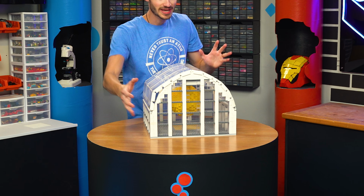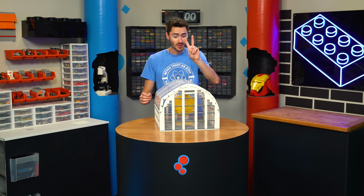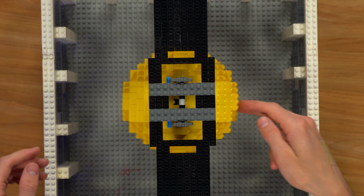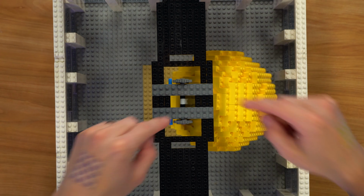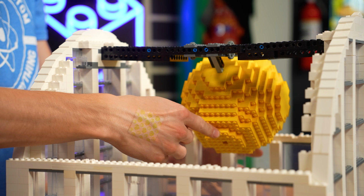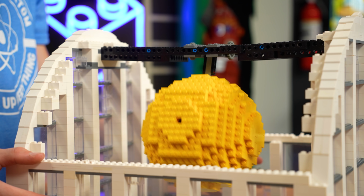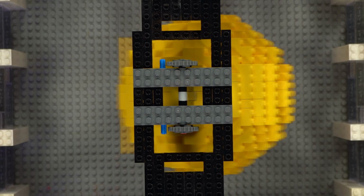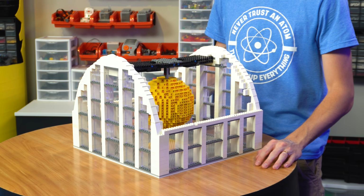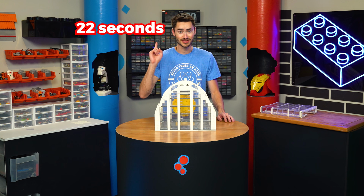So here inside this, we have our tuned mass dampener. And there's actually two ways we can tune this to make it match the fundamental period of the building. As you can see, it's just a big 4-pound ball that swings back and forth, but I've connected it to these gears up here. And right now, the gears aren't attached to anything. So when we swing it, line it up like that. Watch how long it takes for it to stop. Okay, that's how long it took to stop with no tuning.